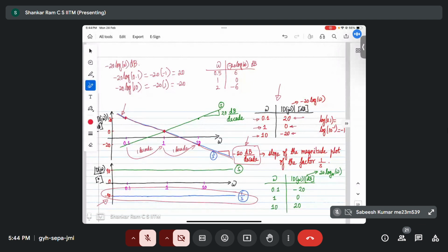So what is the same slope in decibels per octave? Minus 6, right? Very good. In terms of decibels per decade, we go minus 20 decibels. So when we go from a frequency to 1 octave above it, we decrease by 6 decibels. So that's why the slope becomes minus 6 decibels. Is it clear how we got the Bode plot of 1 by s?